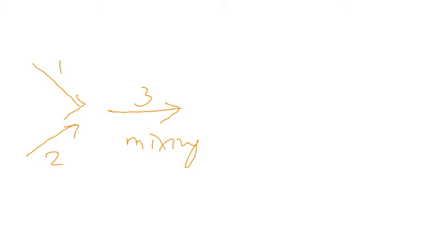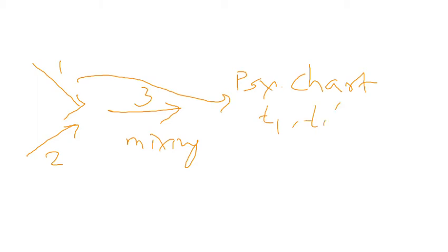So from the psychrometric chart, at state 1 you already know T1 and T1 dash, they are known. Okay, so open your psychrometric charts and find the remaining parameters. The remaining parameters means I want you to find the specific volume V1 and the enthalpy H1. You can pause the video, see what values you are getting, and then check the values which I am writing. Please pause the video, don't just copy it down.